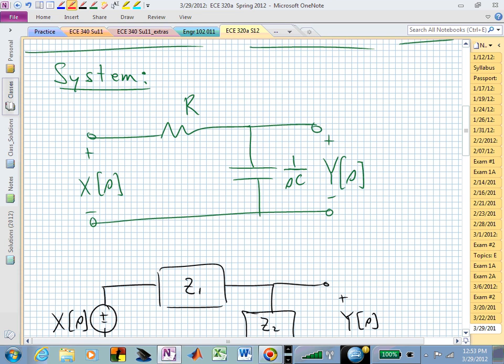And so earlier in the lecture, there was an inductor, but on your quiz, it was just this simple first-order low-pass filter with an R and a C. Earlier in that lecture, I did have a circuit with an inductor. And it was then a second-order system because it had two energy storage devices, an inductor and a capacitor. And then you can do more things with a second-order filter. You will have two poles, and so obviously you could get fancier with what it's doing in the Bode plot or in the frequency response.